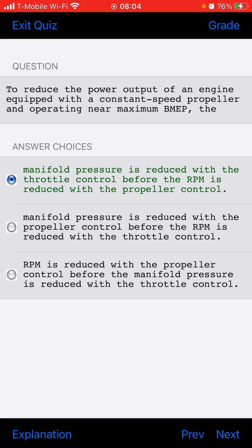Which of the following is a characteristic of the thrust bearing used in most radial engines? Deep groove ball bearings are used as the thrust bearing in most radial engines. This type of bearing is the best of those listed for reducing friction while carrying both thrust and radial loads.